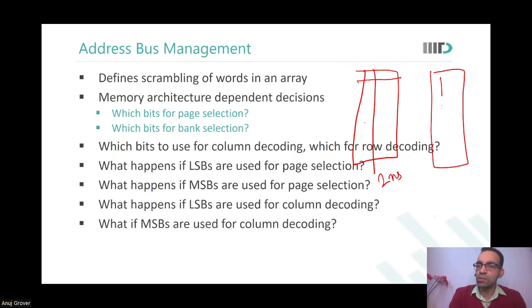Let me split these bitlines into smaller bitlines. Each of these smaller bitlines will be associated with a sense amplifier, and there will be a global line through which I give an output. Now, because the bitline capacitance that every bit cell sees is smaller, the access time would come down to 1 nanosecond, because you have reduced the overall capacitance. So this is called hierarchical bitline.